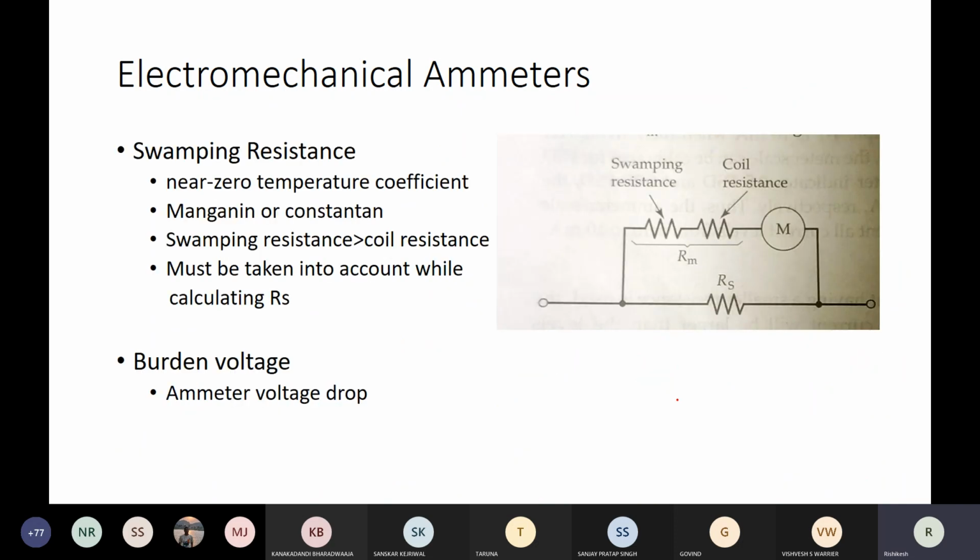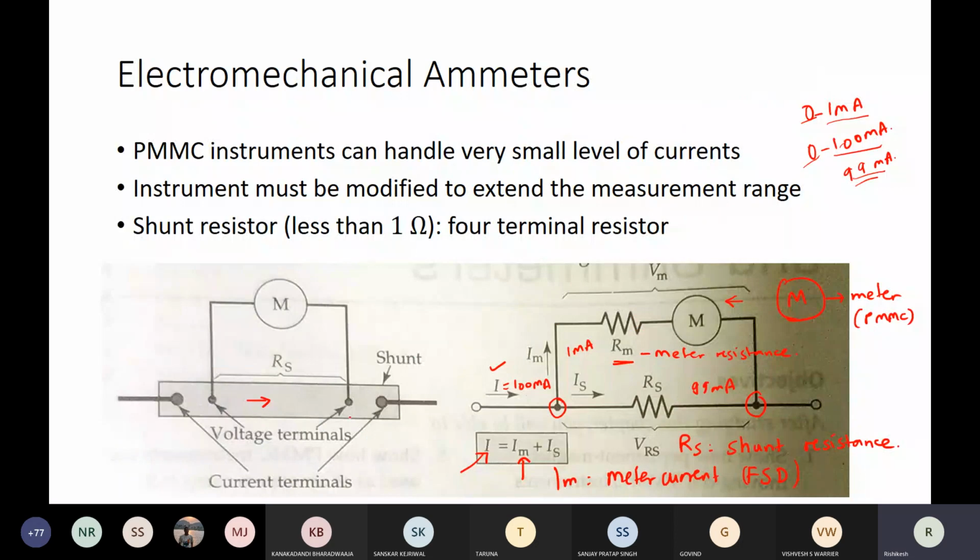Now, one important point I need to mention here is about the resistance which we use for shunt resistance. Remember, even the current carrying wires which you use for making connections have finite resistances which may be of equivalent value to the shunt resistance. So it is very important that you choose the shunt resistance properly, and they are not your common resistances which you use in your 101 or 102 or other labs.